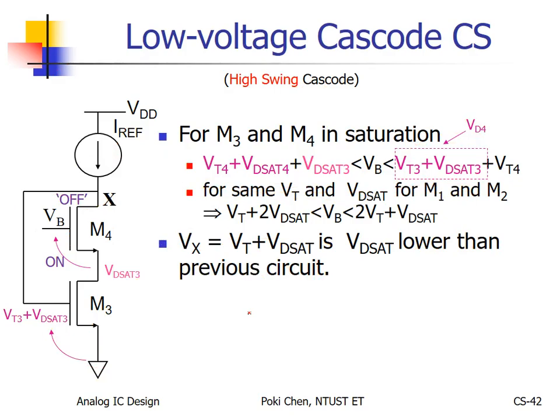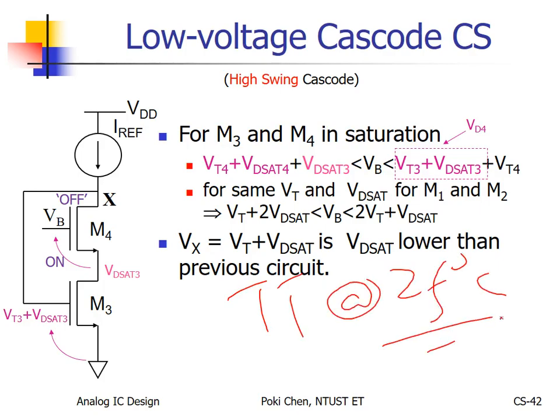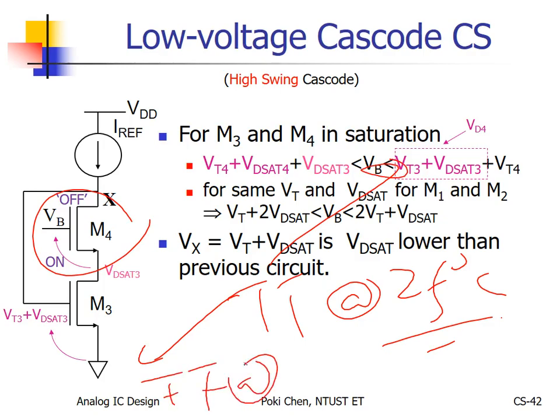Not only for TT, that is the usual case, TT at room temperature. I hope to check whether or not it will survive any kind of process variations. 2 extremes you need to check. The fastest at lowest temperature. Lowest temperature is up to your application.